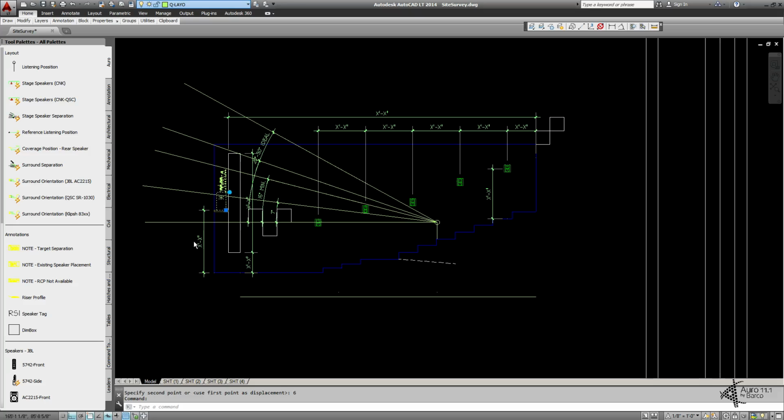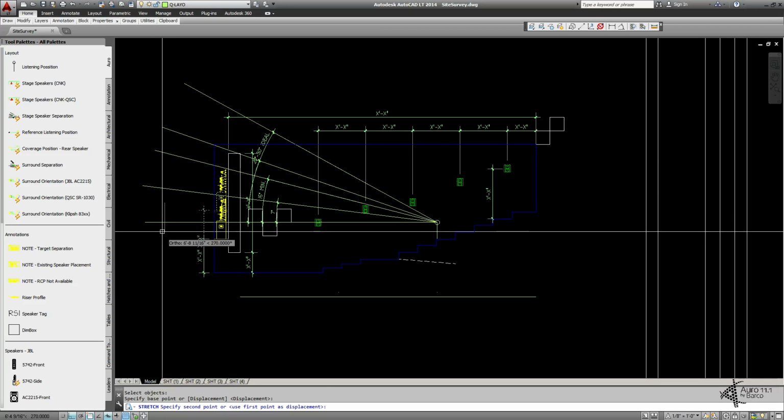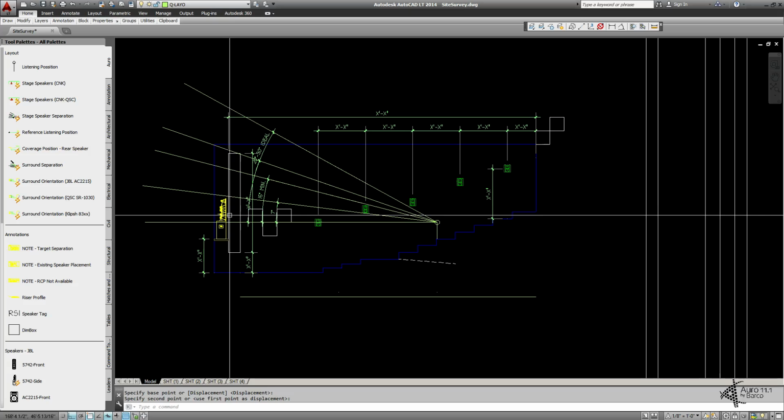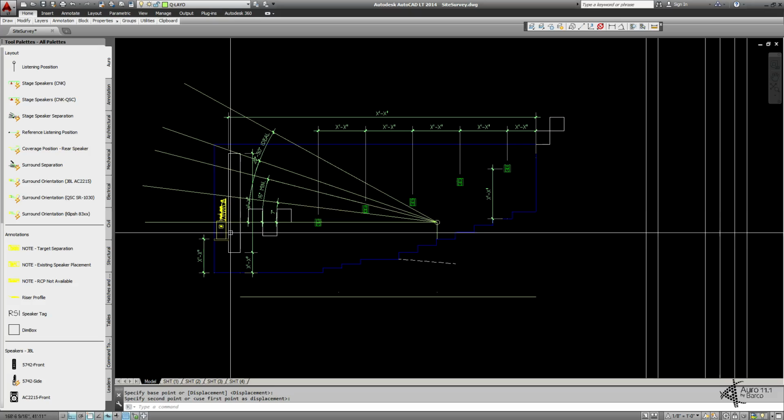Of course you'll use your own layers for your designs, but I've used the AI layering scheme and have some equipment speakers layers, with R for right channel. I'll drop that in there, and as you can see that's really quite high. Typically we would recommend moving that speaker down some. So we'll lower it so that the center is not much more than about 3/8 the height of the screen below the center.